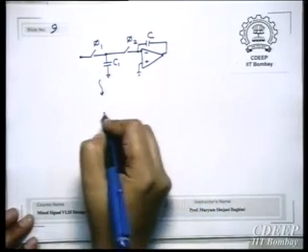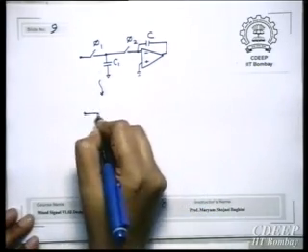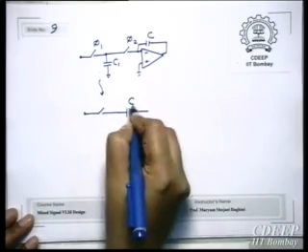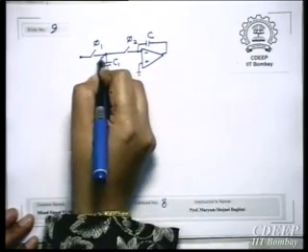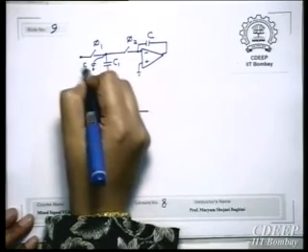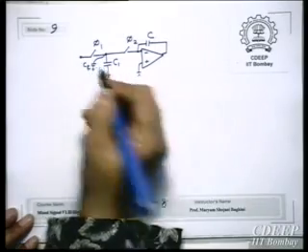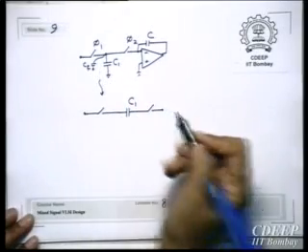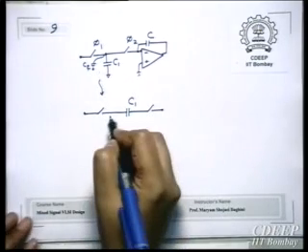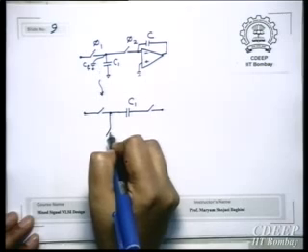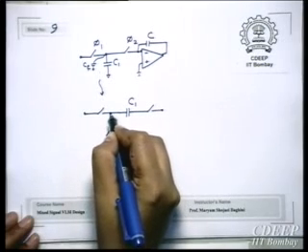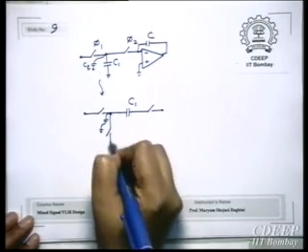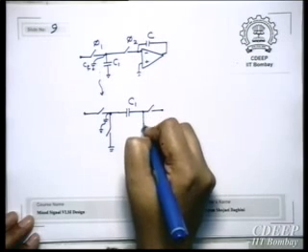So we make just a modification: to keep this capacitor as a floating capacitor. So we have here some parasitics to switch in parallel to this. So we always use it as a floating capacitance, and here there will be another phase which forces any capacitor which exists between this node and ground to be discharged to ground. Similarly here.